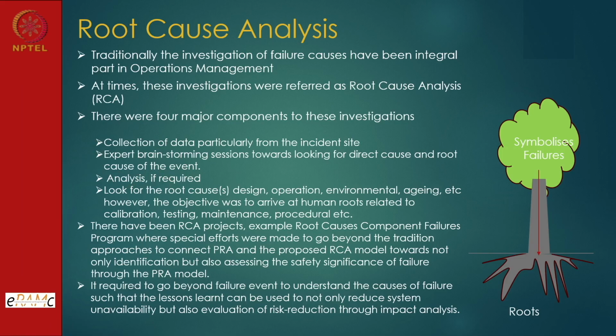And look for the roots, whether it is a design root, operation root, maintenance, environment, aging, whatever root was available, and accordingly. And root cause failure means it is mapped on many other similar things also, so that benefits can be accrued, so that when one incident happened another similar incident should not happen. One of the criteria for the success of a root cause analysis is that this type of event should not happen in the plant again. Not only for that component, but for any component. That defines the quality of the root cause analysis.